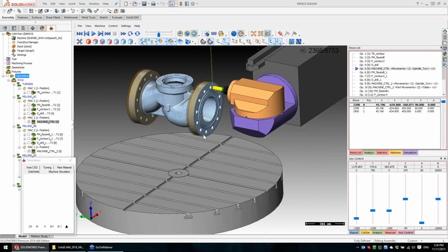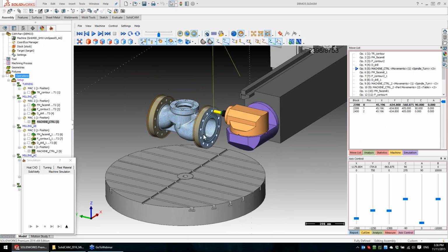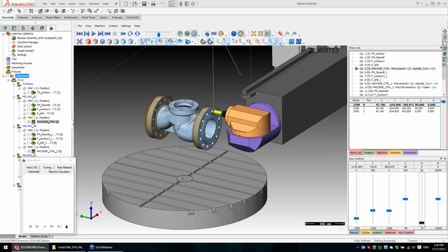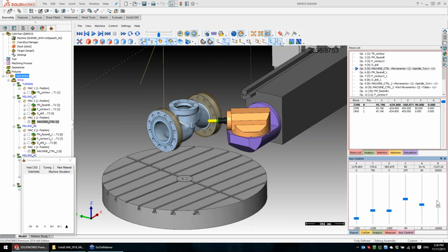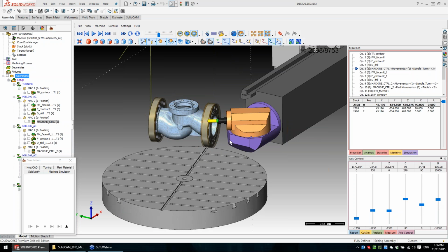Now I want to do the same but with axis A and B. Rotate the table. Before that, axis C, which we already talked about, is not a kinematic axis, not used in the next operation. I will send this axis to 0.